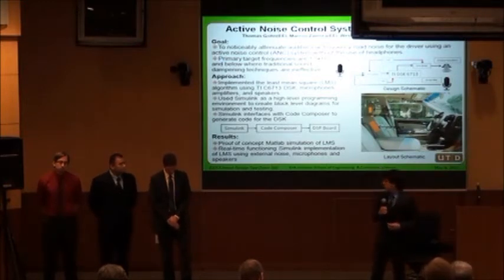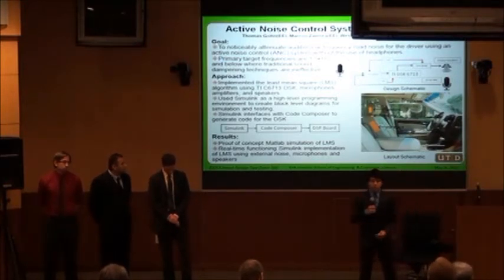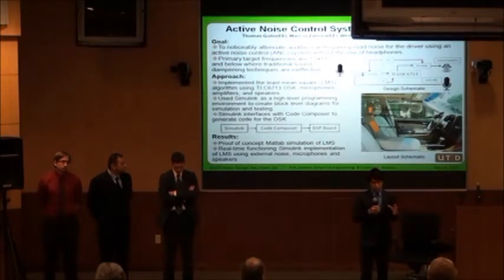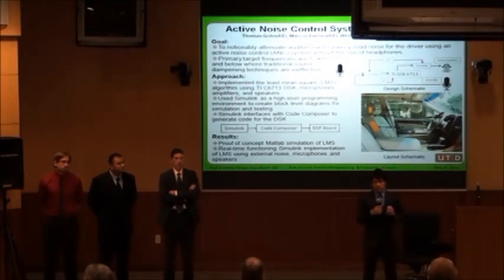And finally, we have our error microphone. This microphone is the focal point of where the road noise and the anti-noise are going to meet, and it creates a small zone around it where the road noise is actually mitigated. Due to this, we have to place the microphone really close to the driver's ears, so the driver also gets a similar effect.